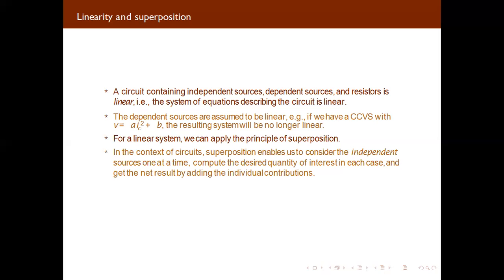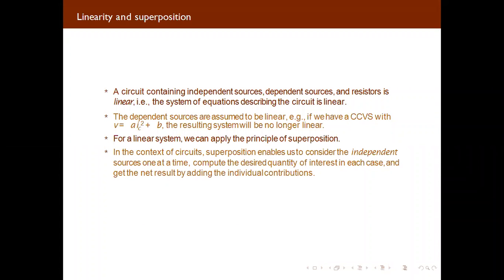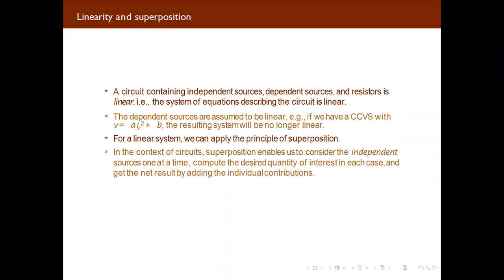So we can say the superposition theorem is valid for a circuit with linear impedance. It is not applicable to a circuit which contains at least one non-linear element, because in the superposition theorem we require only linear elements. The superposition theorem can be used in a network supplied by generators with several different frequencies to compute the values of current, because it will give us the sum of individual currents for each frequency.